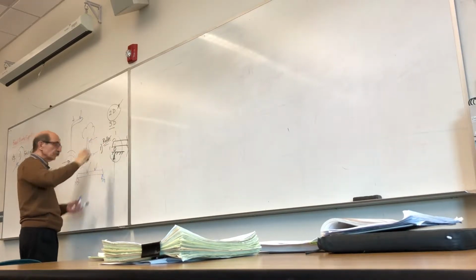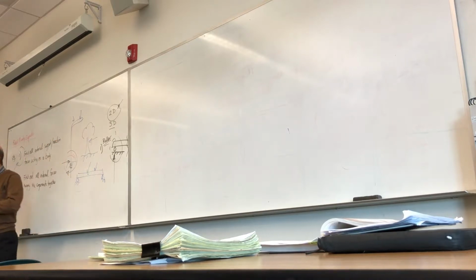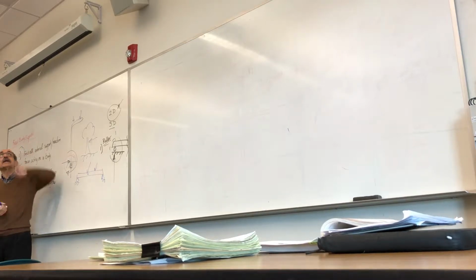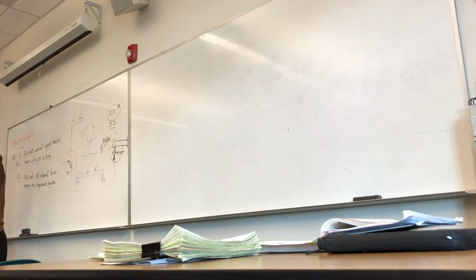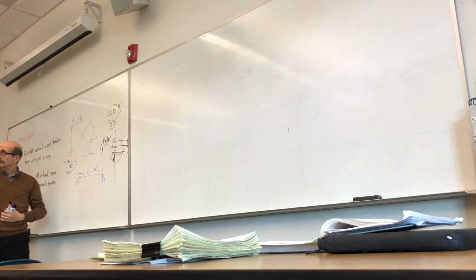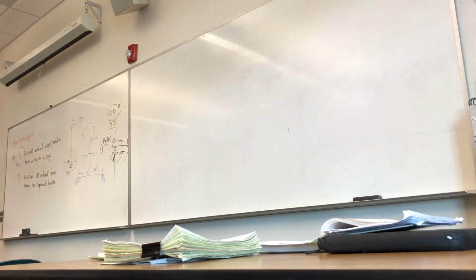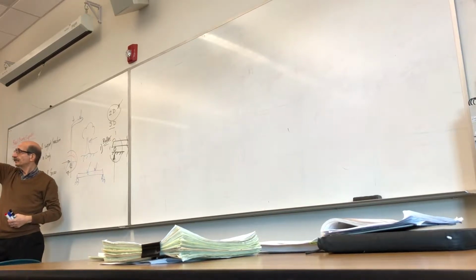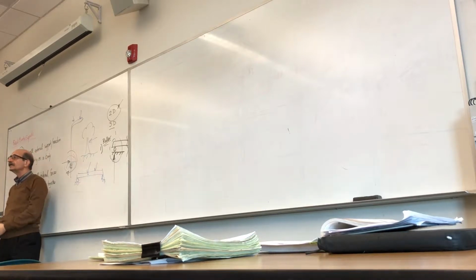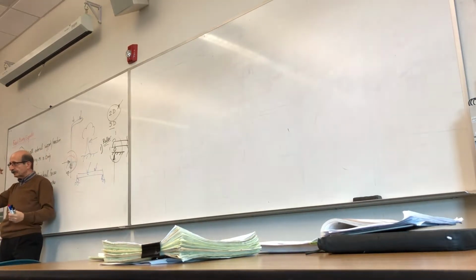Roller doesn't mean that this is necessarily a roller, but it's a mechanism that can prevent motion only in one direction. The cable that is supporting that light fixture allows rotation, right? You can move it also in this direction, right? But you cannot pull it down. So that cable is, in a way, a roller, represents one force.